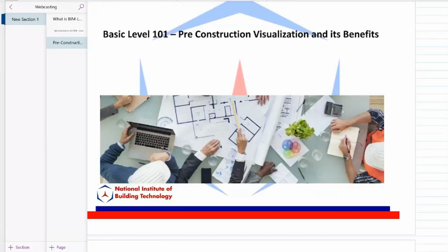With BIM, the whole process, as we know in the construction industry, will change. When the owner hires a design team, and they design using BIM tools, the designs are completely what is called clash free. If someone told me they did Navisworks, they're designed in a 3D world. Elevations, heights, everything is done. That's how they're designed. They'll do clash detection to make sure there are no clashes.